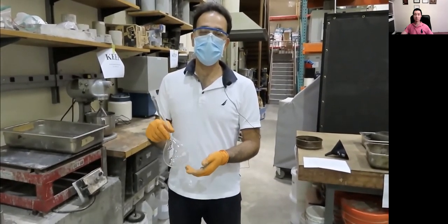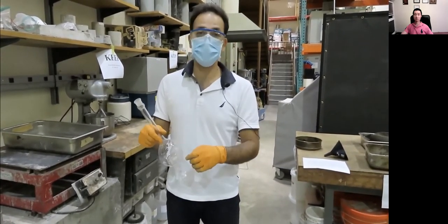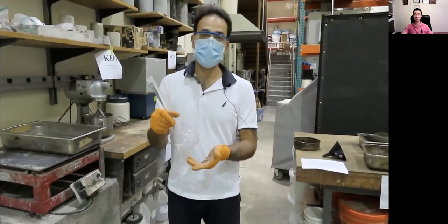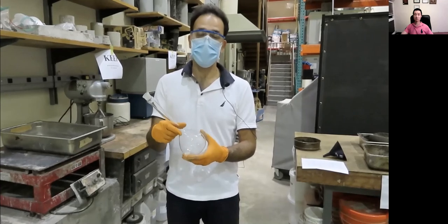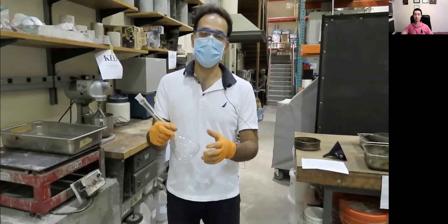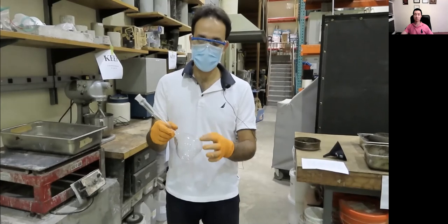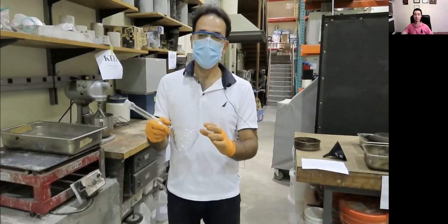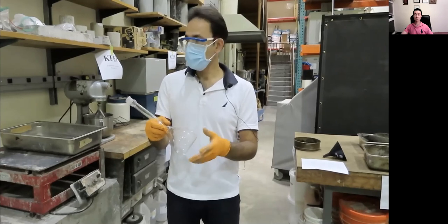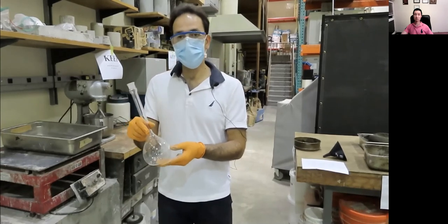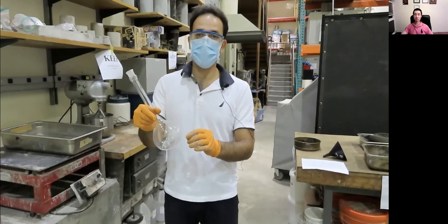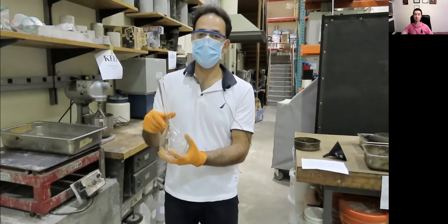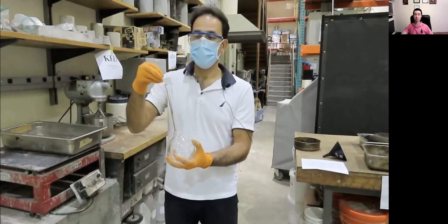So what I did yesterday was wash it up thoroughly and then put it in the oven, because I want to have it clean and dry. I want to be accurate as much as possible. Excessive water inside a pycnometer or on the surface just makes my numbers inaccurate. I need to introduce a bit of water inside the pycnometer, maybe up to here, and then I'm going to dump the aggregate with a funnel.